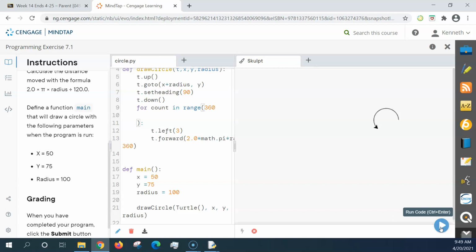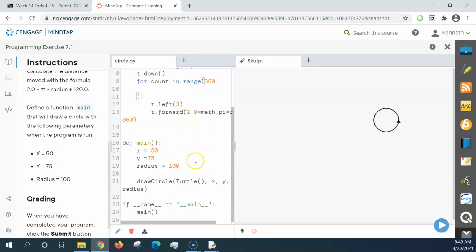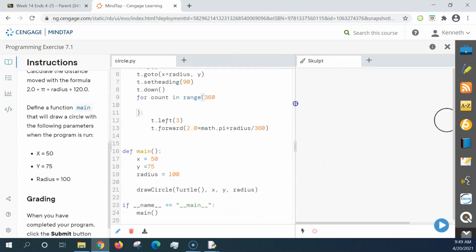So now it draws our circle, and it calculates every point. In fact, I screwed up somewhere. Oh, it's doing it by threes. So in this case, it's going to actually draw it 3 times then. Made a nice heavy line. So it's kind of hard to see in here. So in this case, I would have to actually change that to 1. And now I could draw my circle.